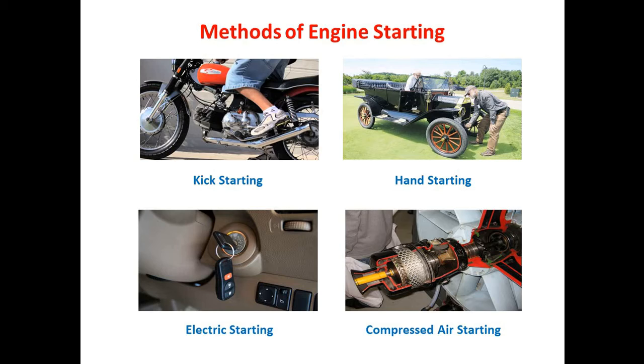Talking about compressed air starting, here compressed air of 20 to 30 bar is admitted in the engine cylinder through the inlet valve, which makes the piston at top dead center move to bottom dead center and create the initial cranking through this reciprocating action, and transfer that to the flywheel in terms of rotating motion. This kind of cranking can also be observed in diesel engines or gas engines utilized in marine applications.